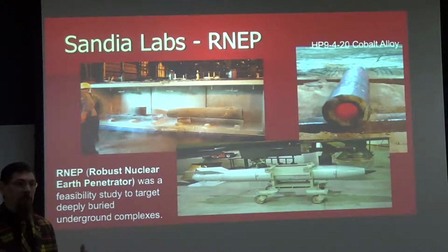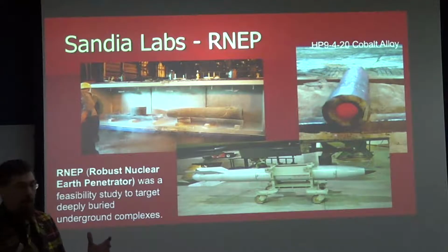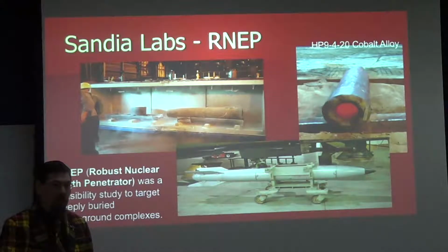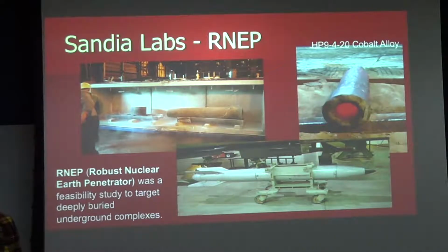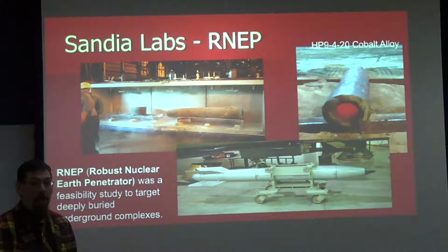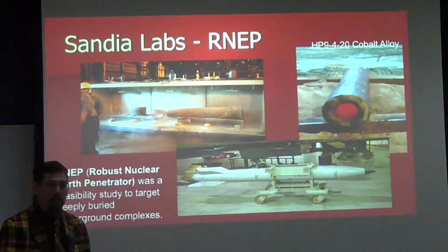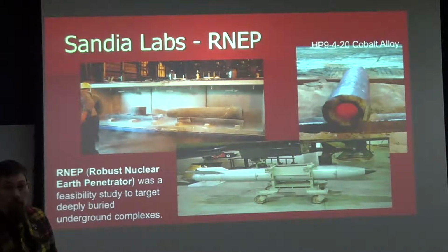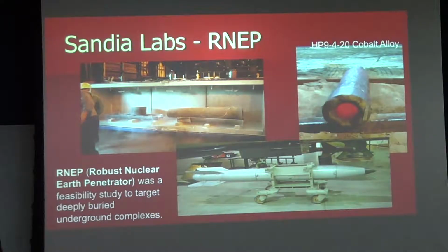There's good reason to take some metals in certain situations and subject them to treatments that are in the -300s, basically submerge things in liquid nitrogen. You can get some significant changes to microstructure and properties when you do that. Perhaps we'll touch on that in one of our history sections. I didn't put it in the lecture yet, but if you remind me, we'll cover it when we get there in a future lesson. It might be something that you could do in your group project to improve the properties of the steel we're going to mess around with. Yeah, absolutely. That could lend itself very well to that type of treatment.